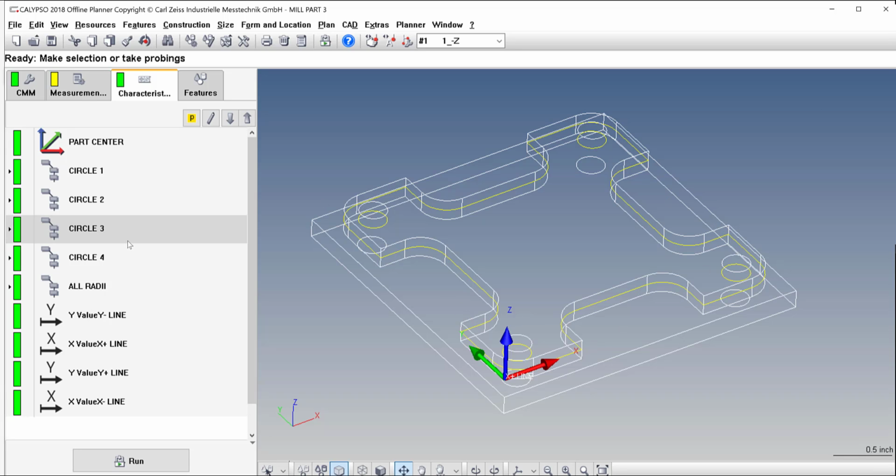All right. I won't do that on video, so I'll pause the video here, let you catch up. Make sure you take care of all these widths the same way we did the other ones: a Y and an X, or Y plus, Y minus, X positive, X minus for each one. Make sure it's labeled accordingly. Then we'll come back once I finish that, and we'll take care of the depths here with caliper distance, and we have a depth from the top of this face down to here. And besides that, that'll be about it for this.